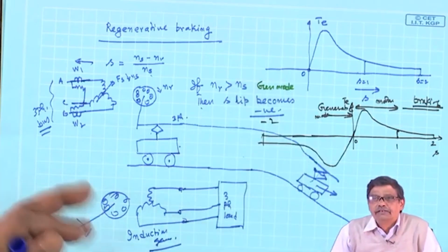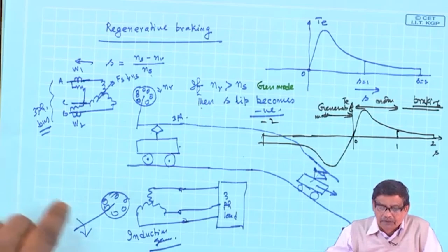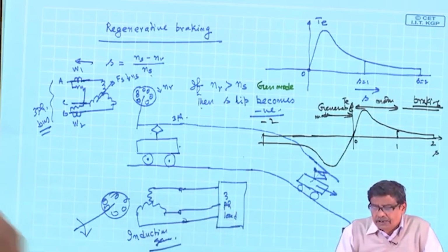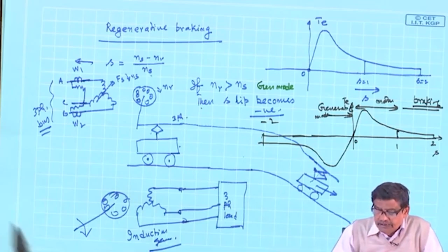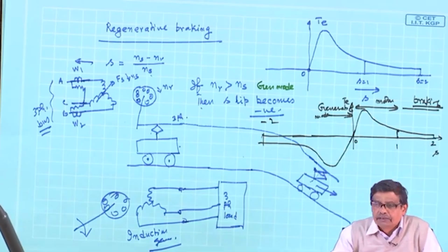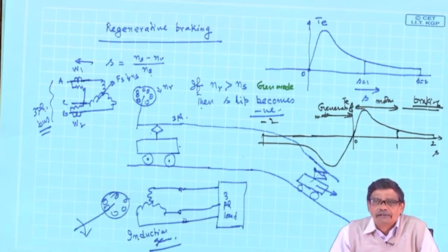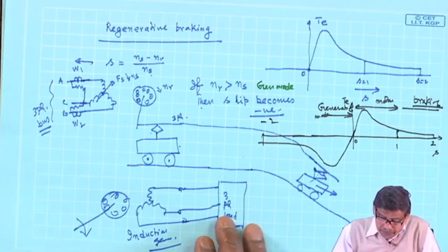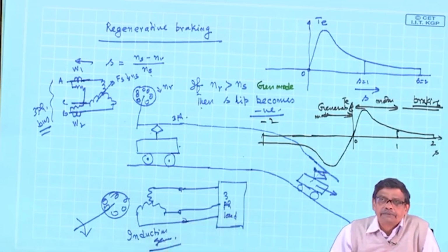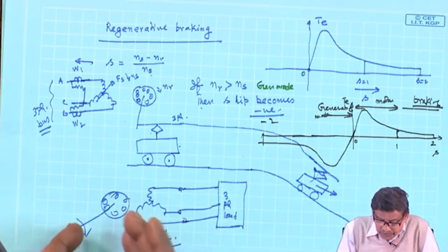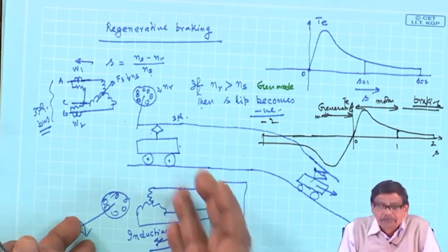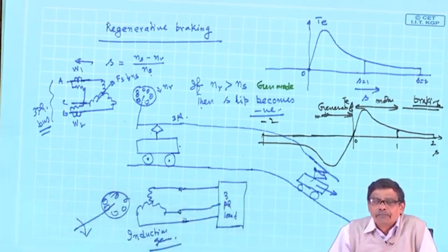After all, you know, diesel set, diesel generator often used. You run the prime mover, diesel motor, IC engine, and you get supply and then load. No question of bus coming anywhere. So, can induction motor be operated in this fashion? The answer is yes, it can be operated, but as it is, if you connect like this, you do not expect any voltage to be developed.